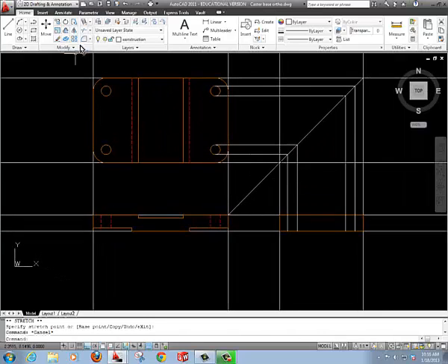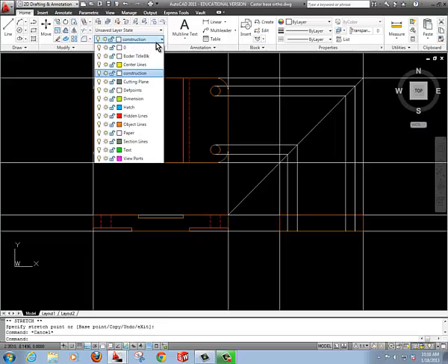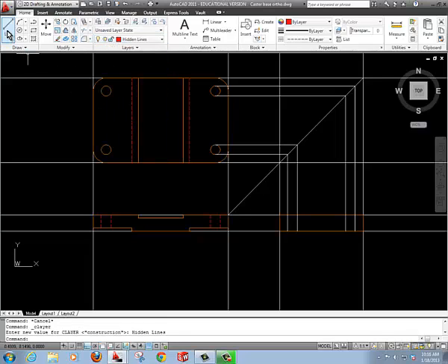Now we're going to go and put our hidden lines, because that's what we need to finalize this object. So we have this hidden line right here. Now this feature right here gets transferred as a hidden line also. So we can come over here to the end, acquire that point, and draw our hidden line this way. Now this one becomes an object line because we see that face right there. So we go to our object line, go from this point right there, and come back to the other side.